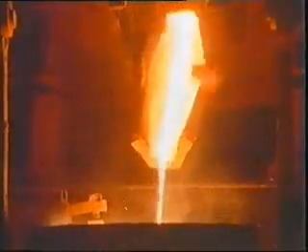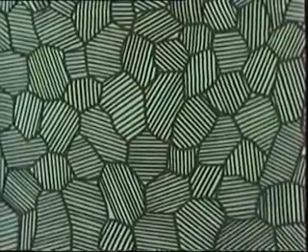So far, we've only looked at 0.4% carbon steel. However, steel can be produced with other carbon contents. What effect does this have on the grain structure? We'll start with 0.4% carbon, and let's add some more. Can you see what's happening? The number of pearlite grains is increasing. Now there are no ferrite grains at all. The steel now contains 0.8% carbon. Under the microscope, a similar piece of steel looks like this.